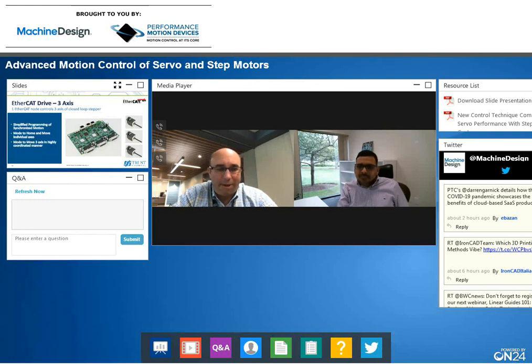And I would be very much at fault if, when I was talking to the gentleman who designed this board just before this call to make sure I wasn't going to say anything dumb, he did bring up one of the things that he would like people to realize. We have single turn absolute encoders that we put on the back of these motors. PMD allows you to pre-program a phase angle, which isn't commonly offered in this application. So it allows you to not have to go through some bizarre phase alignment algorithm initially when you start up to get your phase location to your pole location figured out. You can actually do that in a factory calibration.